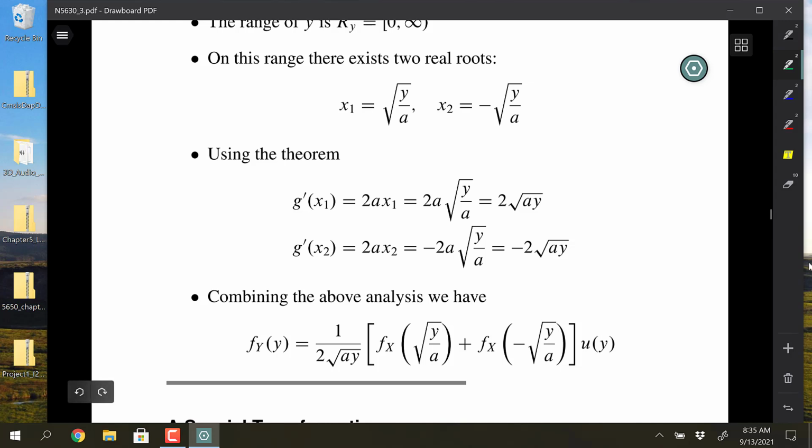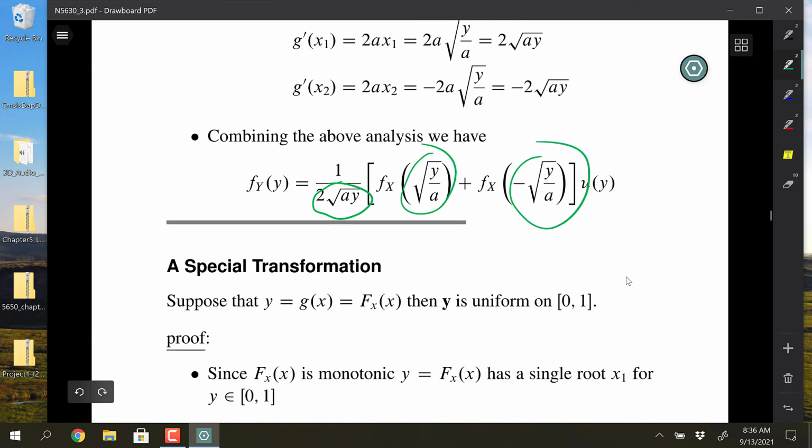And what's pretty obvious right here is that is definitely nonlinear sitting in the denominator, and then you also have the square root sitting up in there. And square law devices are used for power detectors in signals and systems. And why do we care about power detectors? We want a gain level. We want to have automatic gain control, some means of regulating the amplitude of a signal that's going into an A to D converter in a digitizer, which would be a function in a receiver. You got to match the dynamic range of the input into the A to D.